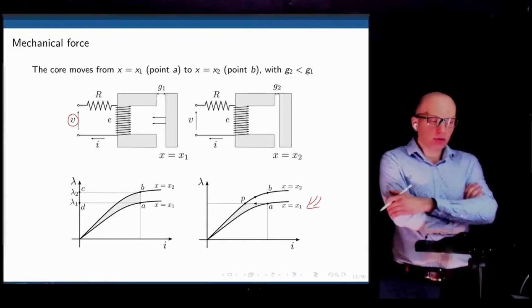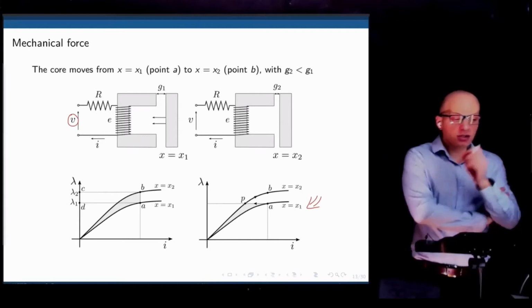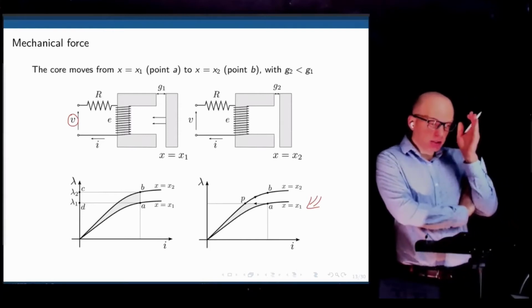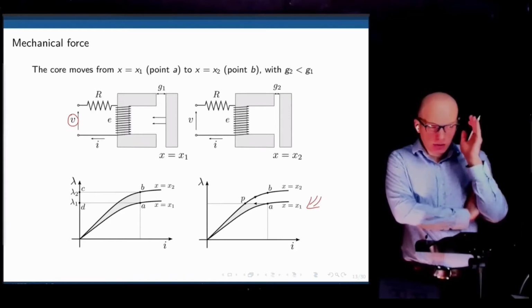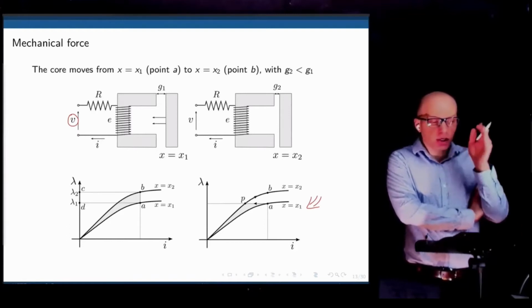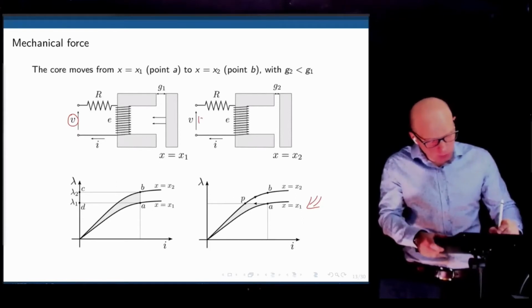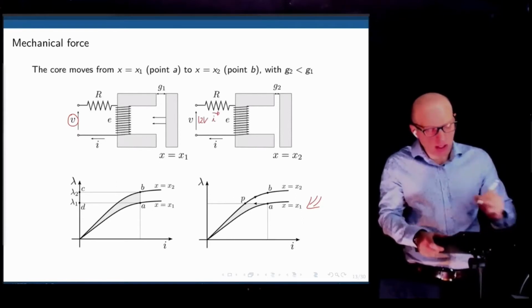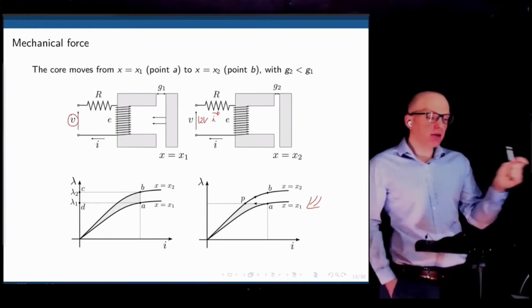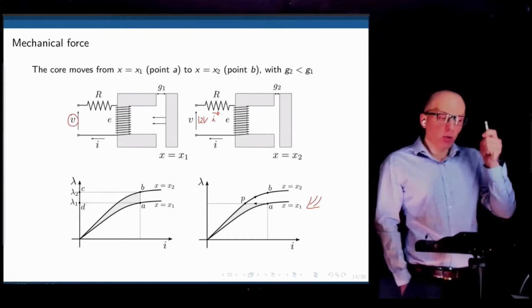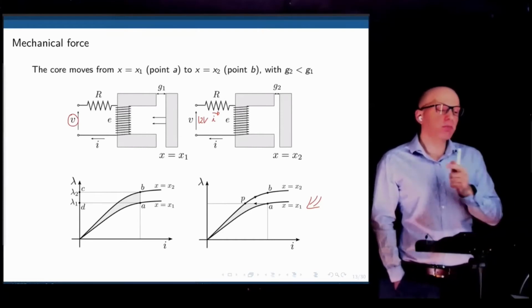It is a decrease in volume in the air gap, yes, but this decrease will only occur during motion. Once the plate stops and reaches zero speed, the current goes back to its nominal current. So if you apply, let's say, 12 volts here and you have 1 amp going in, if you move the plate back and forth, during motion, that current changes. But when the plate stops, the current goes back to 1 amp.